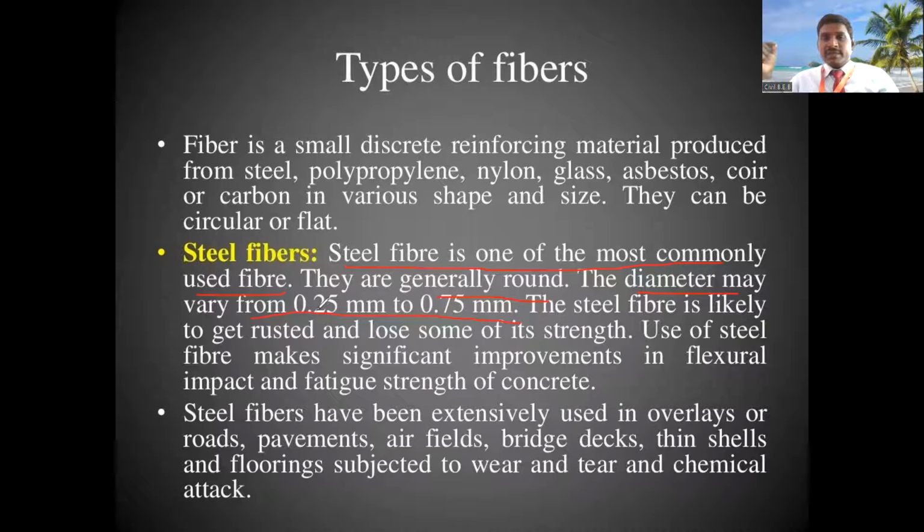Then, the steel fiber is likely to get rusted and lose some of its strength. The use of steel fiber makes a significant improvement in the flexural, impact and fatigue strength of the concrete also. So this is some of what we can say about the steel fiber.